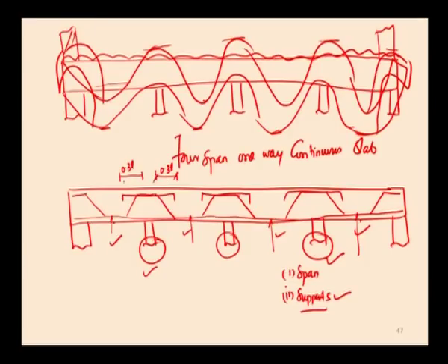The total length of the reinforcement is 0.3 L on either side of the face of the support plus the thickness of the support. We are not normally providing the extra reinforcement at the end support, since only a partial restraint is developed over this support. To resist that partial restraint, 50% of the reinforcement is more than enough.